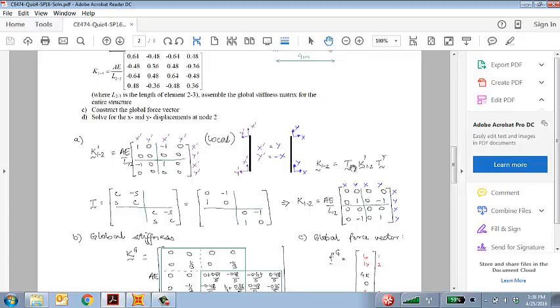But if you go the transformation route, it does involve a fair bit of calculation. As you saw in the homeworks for any vertical element, and I think I pointed out in the lectures also, it is the same stiffness matrix, except now instead of these 1, -1, -1, 1 being in these positions, they are now at the 2, 4 positions instead of 1, 3 positions.